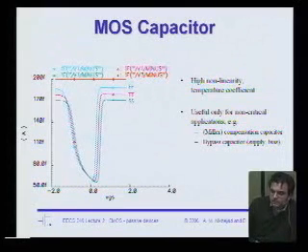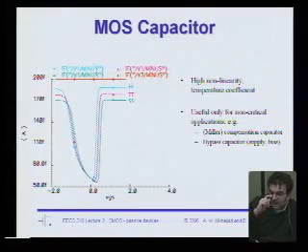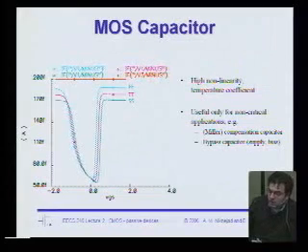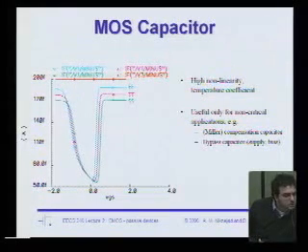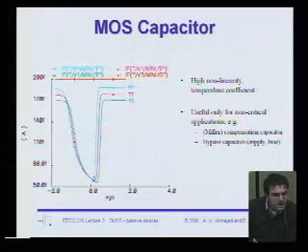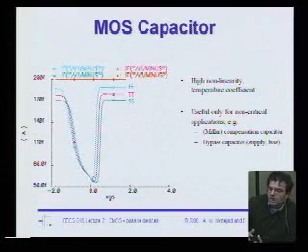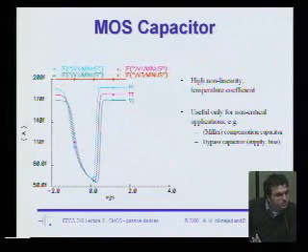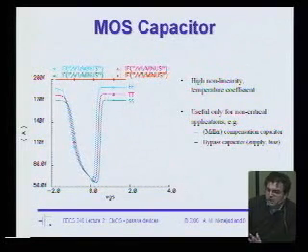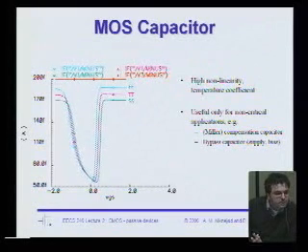The traditional way of doing analog design, and also digital design, circuit design in general, has been make sure your circuit works for all process corners. Now, process corners in some ways are very artificial. You're never going to get a transistor that falls exactly within the corner. But the idea is that if your circuit works across all the process corners, then very likely, on average, it'll work. Okay? Now, that way of design will probably change in the next few years.